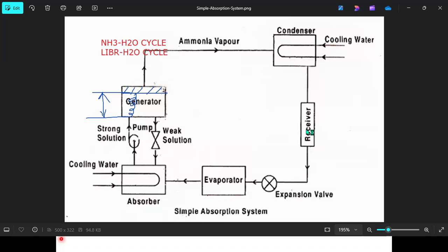Now we will be getting a low pressure, low temperature fluid, still in liquid. It doesn't get solidified. Why? Because the freezing point of ammonia is very low. So after crossing this expansion valve, this high pressure, medium temperature liquid ammonia becomes low pressure, low temperature liquid ammonia. Clear? And this liquid ammonia should be carried over to the evaporator, and the evaporator is placed right inside the room where you need the cooling effect. Is it clear, guys?